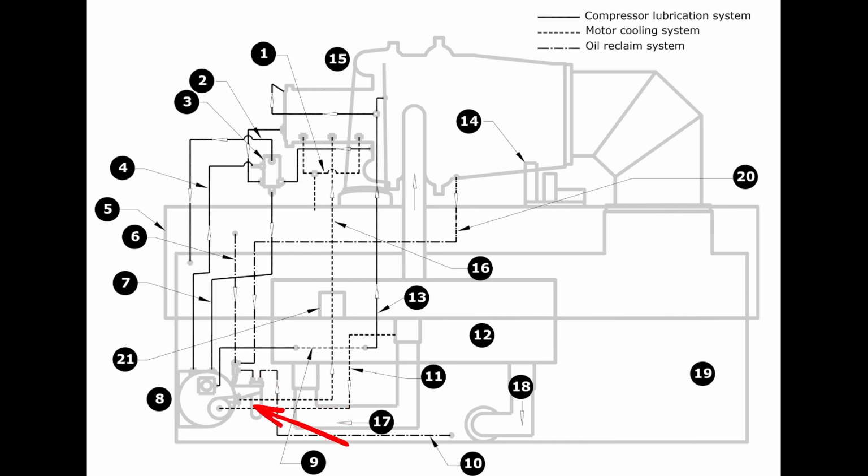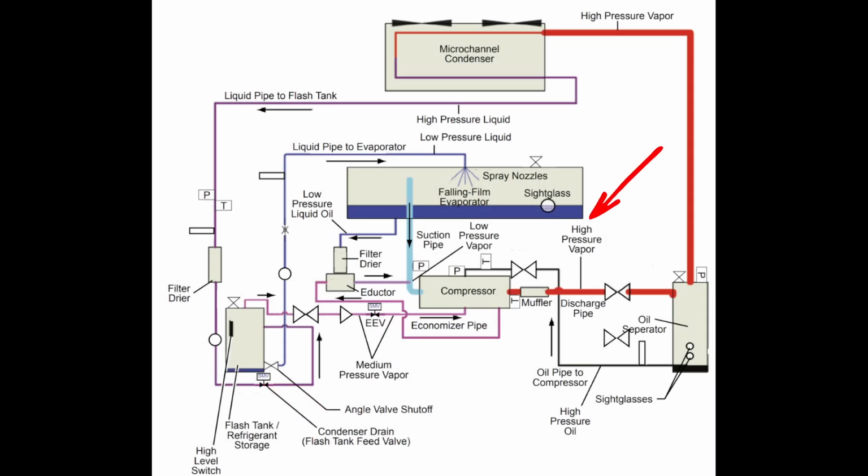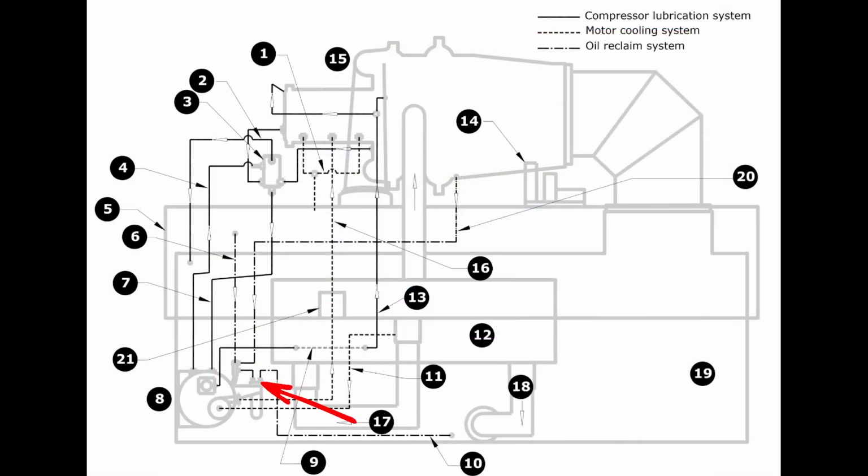So this is actually a filter dryer, just like what we were doing in the YVAA example over here, except some of these I've actually seen are just flared liquid line dryers being used. Specifically the larger ones are this kind of canister style. They look different, but they don't look like a liquid line filter would look. They're a different style of dryer.